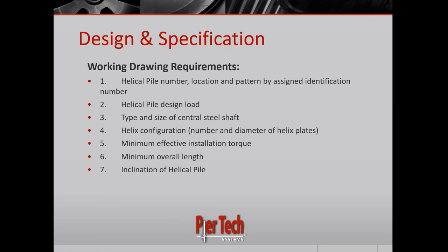If you're doing a pile at an angle, you can start the pile vertical, and then once you get it embedded a little bit into the ground, you can start pulling it towards the angle you're installing. So you start it out vertical, get it in 6 inches or so, and then start moving it out at an angle, so that once it's in there and you've got the right location, that it's not going to walk on you during the installation.